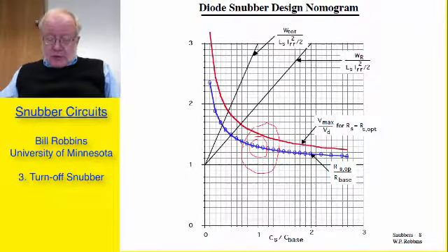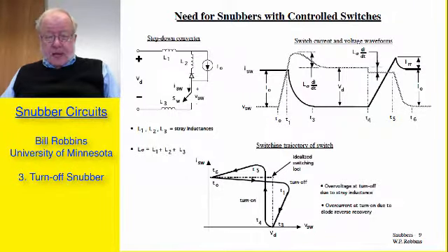The next kind of snubber that I want to talk about is for control switches, that is MOSFETs, IGBTs, field control thyristors, and all of the other devices that are three-terminal devices, namely 2 output terminals and an input control terminal. I'm going to have my discussion in terms of a simple step-down converter where I have stray inductance perhaps scattered through several different places in the equivalent circuit.